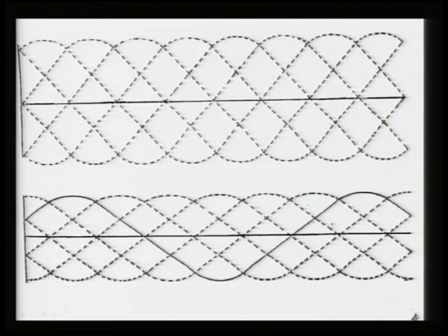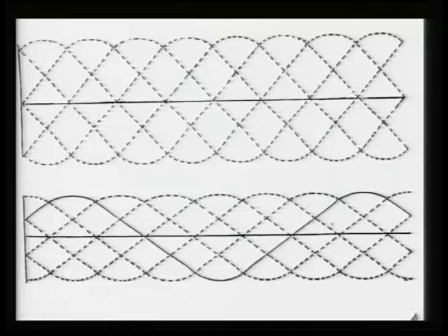So, to draw the output voltage and as well as the voltages across any of the valve, we have to draw the line voltage on the graph, and here we are taking, since we are starting with the 3. So, the commutation voltage of 3, just it is EBA, and then we have to write other phasor voltages here, the line to line again it is CB, here it is your EAC, and again we are going to have EBA here.